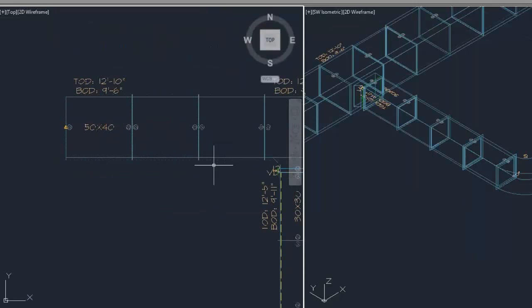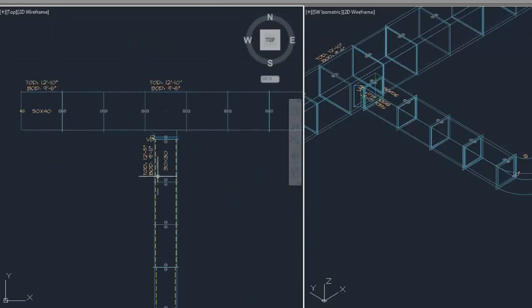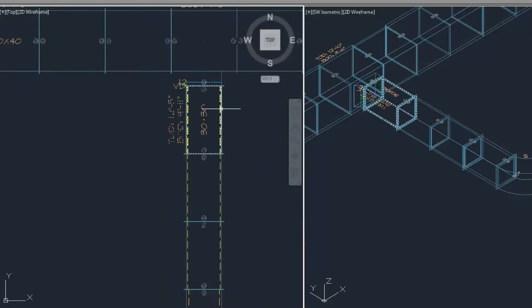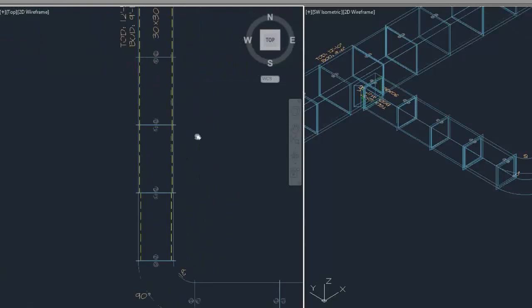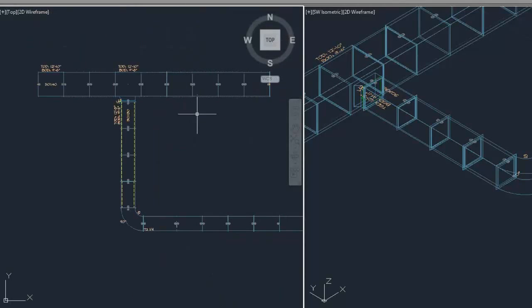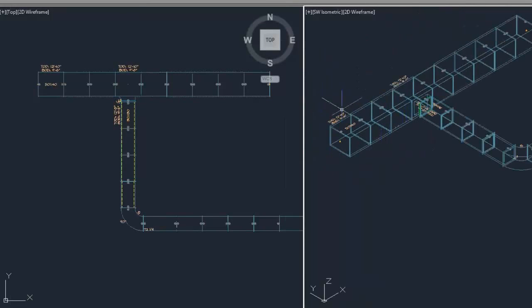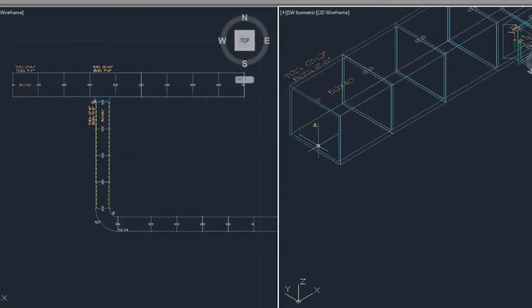So now I see the dots on the outside where I have insulation, and now for my lining I get a hatched or hidden line type inside of there. Looks a little bit better than what the solid lines do. Now we'll come back in and we'll do the same thing for the model display or isometric display.